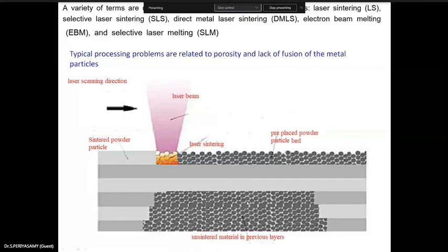For example, the magnetic method is not applicable for mechanical properties as well as geometric properties, then the surface roughness. For the remaining, microstructure, then cracks, porosity, voids, you can find them from this magnetic method. Similarly, residual stress you can find. So you have a correlation between the methods and the